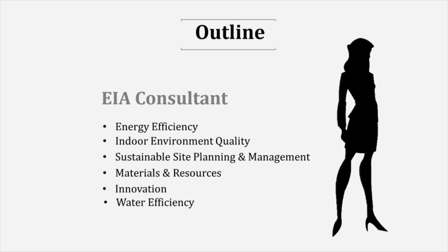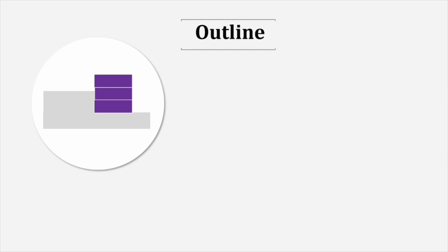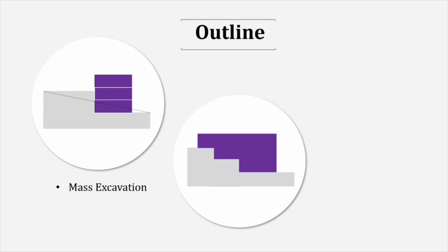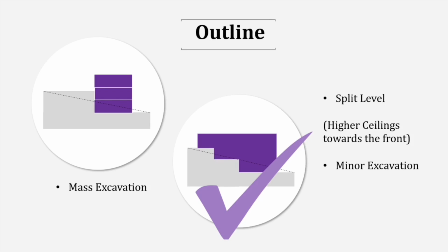Here we face our main problem in constructing this bungalow, the steep slope. Normally, cut and fill will be used to level the site. However, this involves a mass excavation which damages the site majorly. Hence, it is more environmentally friendly to incorporate a split level design in the project, which has higher ceilings towards the front. This will require less excavation, thus having a smaller impact on the site.